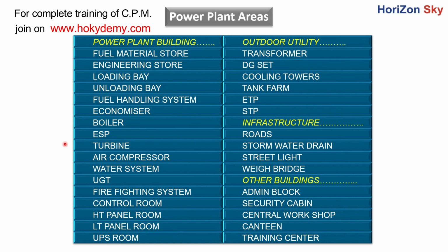In that case, some amount of steam from the boiler will be sent to the industrial area for utility purposes, and the remaining steam will then be used on the turbine for power generation. So this is a composite kind of model in some industries or industrial campuses, whereas if it is an exclusive power plant, then all the steam that is generated from the boiler is used for power generation.